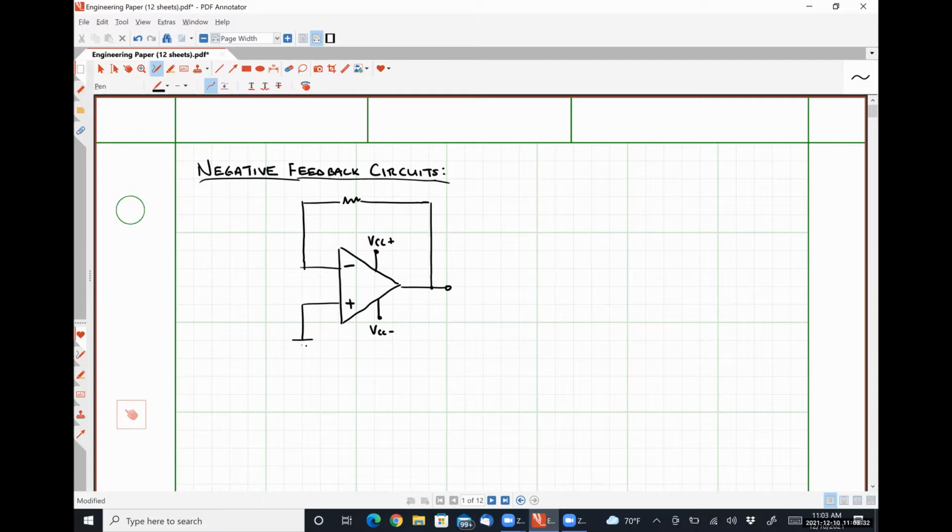the feedback resistor. So let's call this guy up here R sub F for now, for feedback resistor. And it's a negative feedback resistor because it's connecting the inverting terminal to the output terminal. For positive feedback, which is what we covered on Wednesday, we were connecting the non-inverting terminal to the output. This is going to be our output voltage, the output.